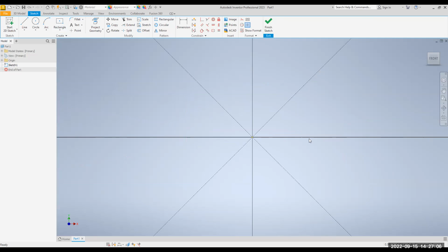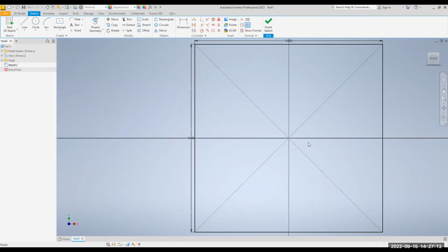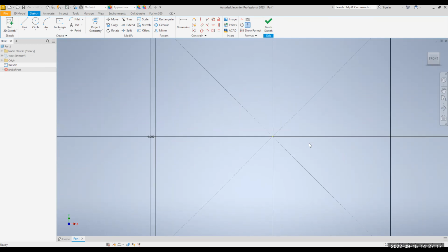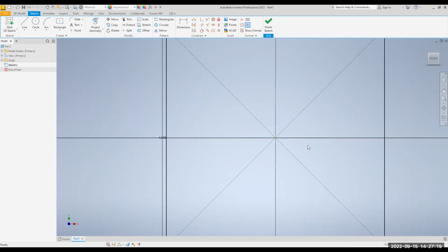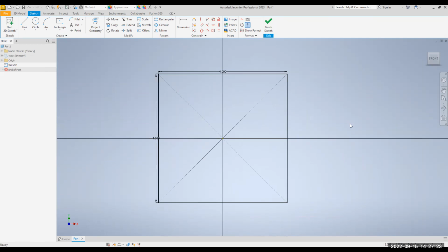All right, so you can't see the geometry, but if you take your scroll wheel and rotate it, you can zoom in and out. For those who haven't had too much practice with Inventor, the scroll wheel will allow you to zoom in and out. Hold down the scroll wheel and move your mouse and you can pan. So again, this is a good review for most of you, and new for some. Up here you have your view cube, right?